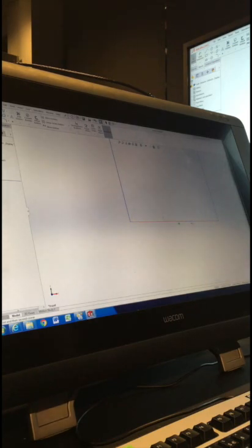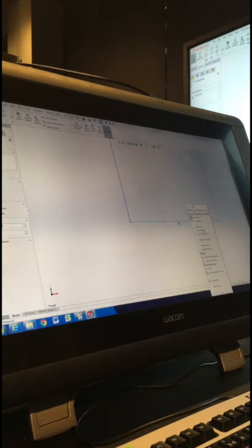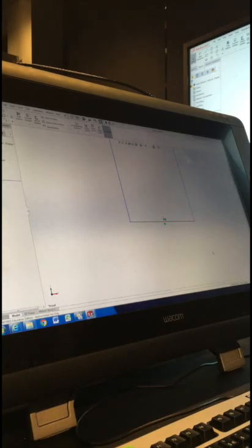On that line at the bottom, right click on the line and select the option that's select midpoint. Now that's picked up an imaginary point that's at the middle of the line for us. We can then hold Control on the keyboard, select the origin, which is the red arrow, and make it coincident. What that does is puts the middle point of the line on the origin, which means that this part is now going to be symmetrical around the origin.